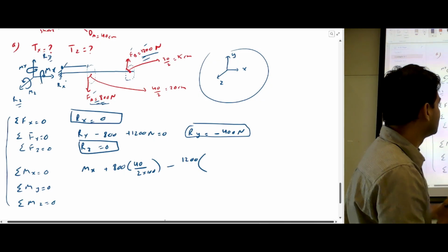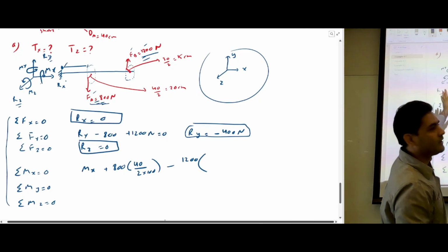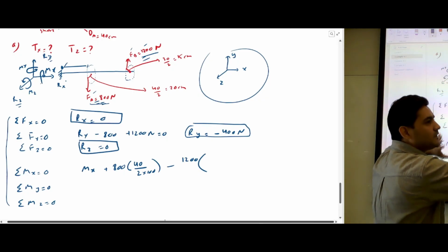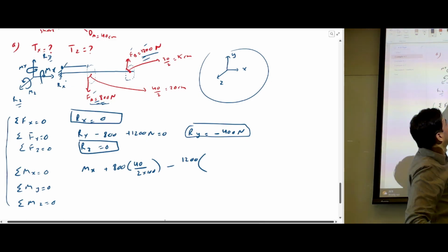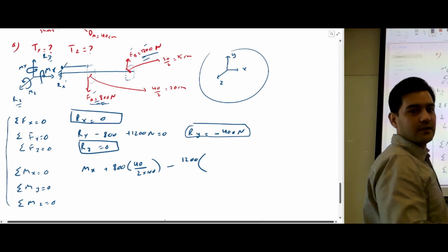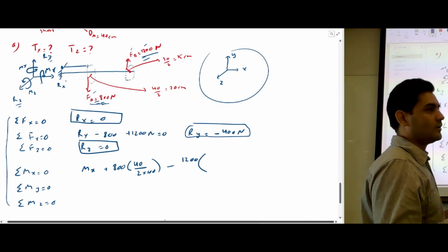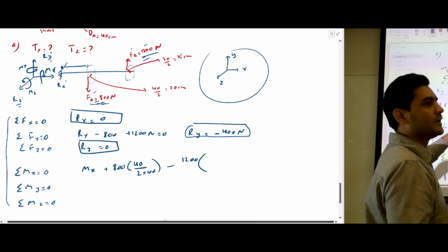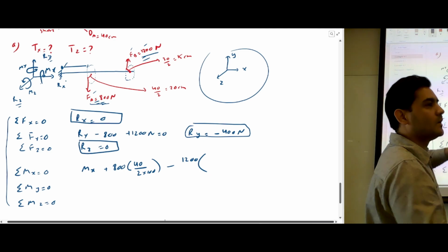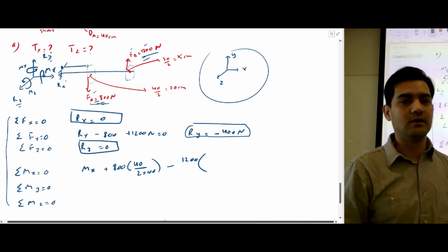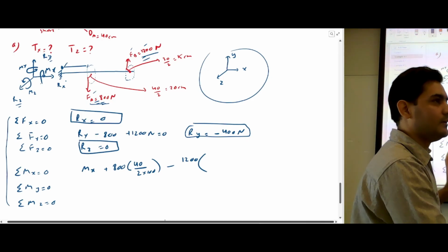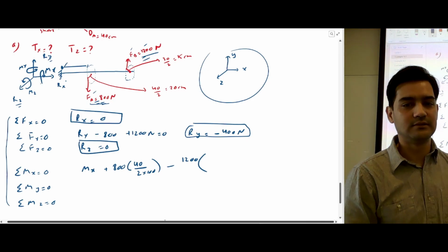Yes, you should. This is just 3D. This is the first example, but otherwise I will give you another way: instead of drawing this way, we should draw a double arrow. Then we're not going to make a mistake. But for sure we should be consistent. This is a simpler example, that's why we're going to get the right answer anyway. But otherwise, yes, whatever we have assumed in a free body diagram, we should stay consistent.